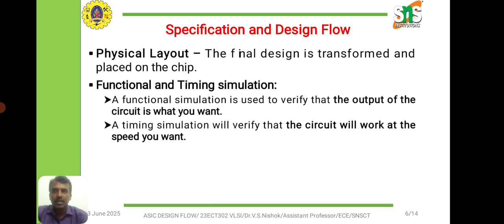And then once that mapping, placement and routing is done, then final verification takes place. So that is timing simulation, which represents how speedily the circuit that we are designing is working, so how efficient it is, that is checked with the help of the timing simulation.